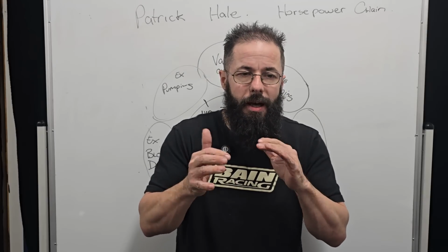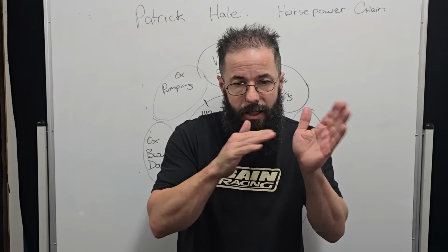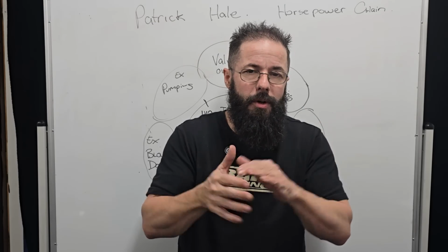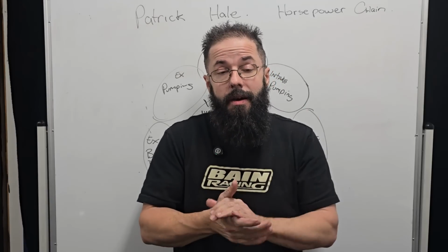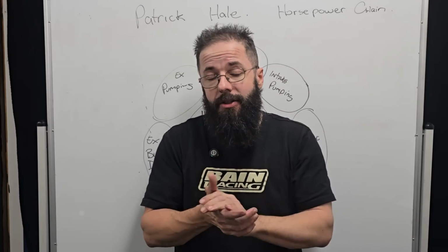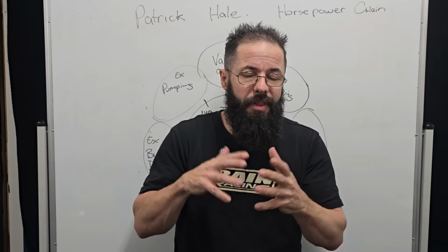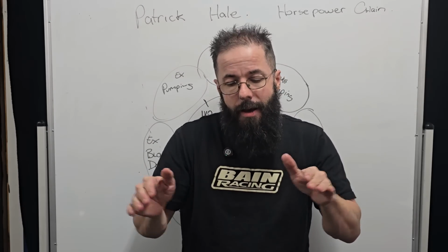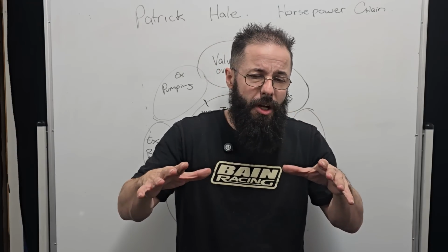Now with the chamber, again, this is why I say we need to look at LSA, because LSA and that exchange rate and how efficient the chamber is. So a wedge head will be nowhere near as efficient as some of the modern LSs and the Fords and what I talk about tomorrow night with the big block 9 degrees and some of the like Blue Thunders and stuff like that have an absolutely beautiful discharge coefficient.